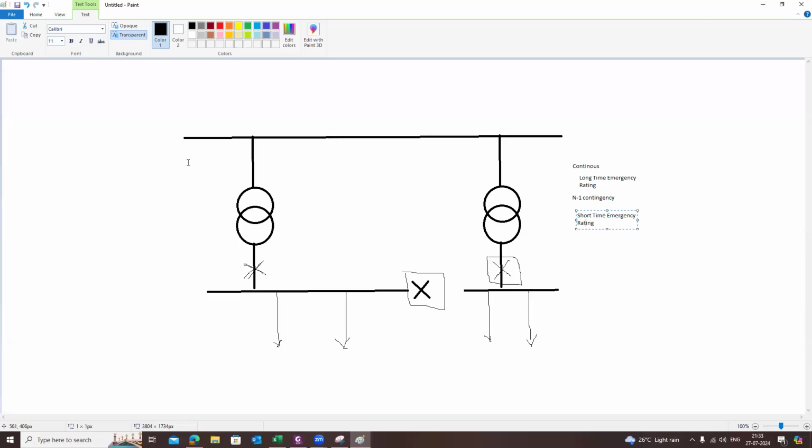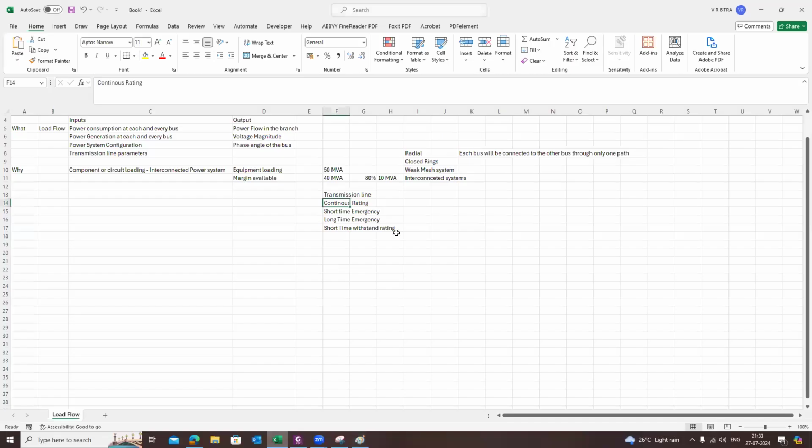And in addition to that, this load flow will give the details, it gives the information about the available transfer capacity, which we will call an ATC. Say, for example, for each and every country, there will be a load forecast, and the loads will keep on increasing, right? Definitely the loads will grow because we start consuming more and more electrical energy. If we plan the transmission line for today's demand, it may not be sufficient for the entire lifetime.